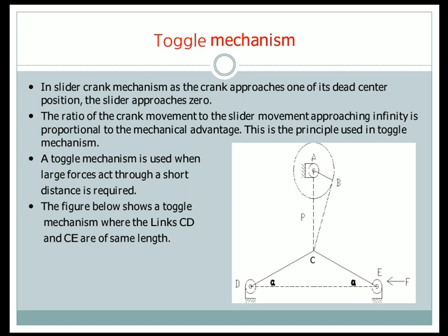A is a fixed hinge and the link AB will rotate through a circle as shown in the dotted line. And here there is no link AC. They have indicated it by a dotted line, but there is a link BC. So when the link AB is rotating and when it is exactly vertical, it will coincide with the line AC.